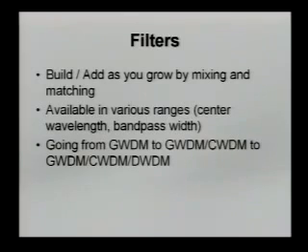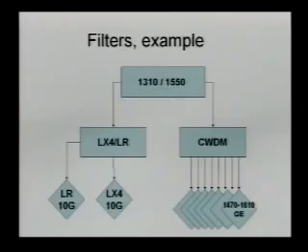Why is WDM very interesting for somebody who has operational experience and is trying to build a network at low cost? Basically, you can grow it. When you have a system which is WWDM with 2 channels, you can add more filters and extract more wavelengths and scale it up as you grow.